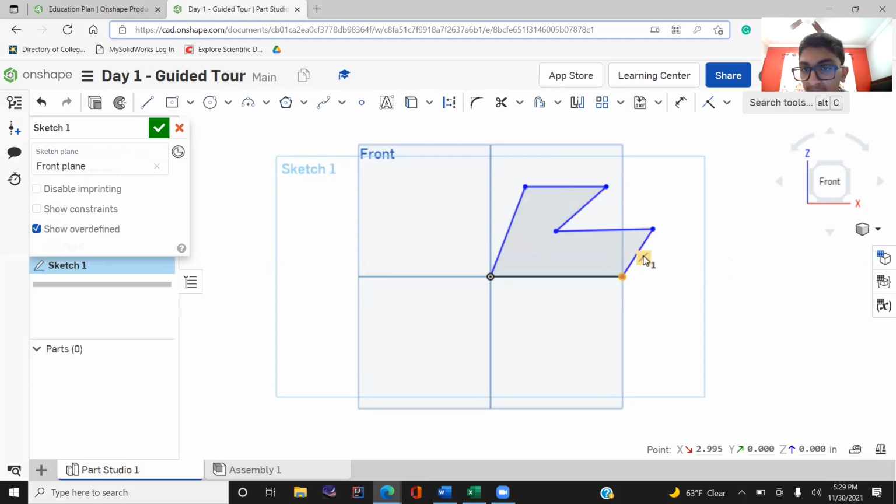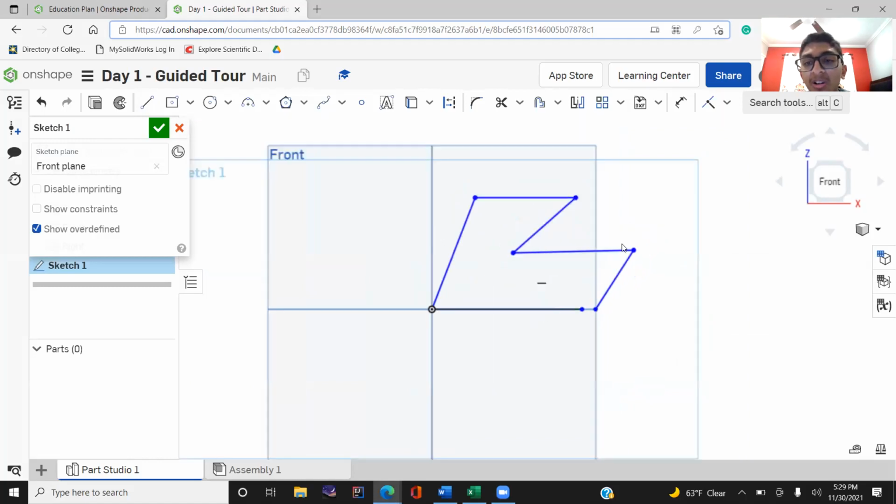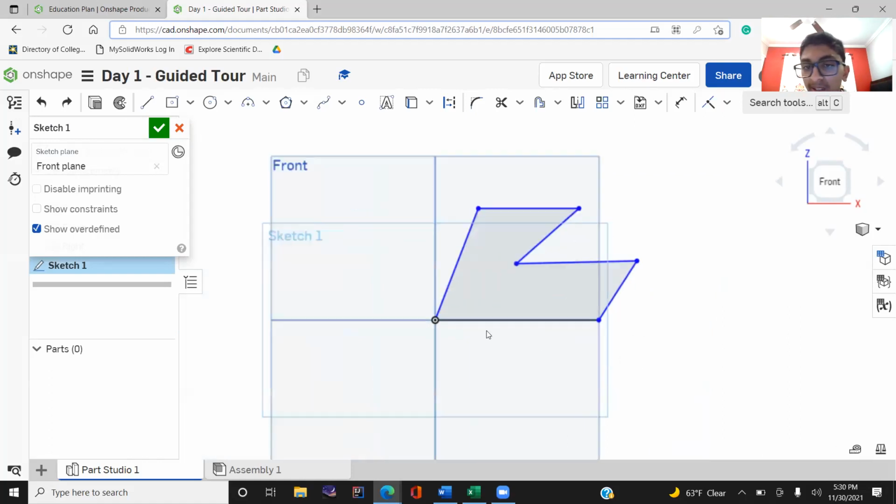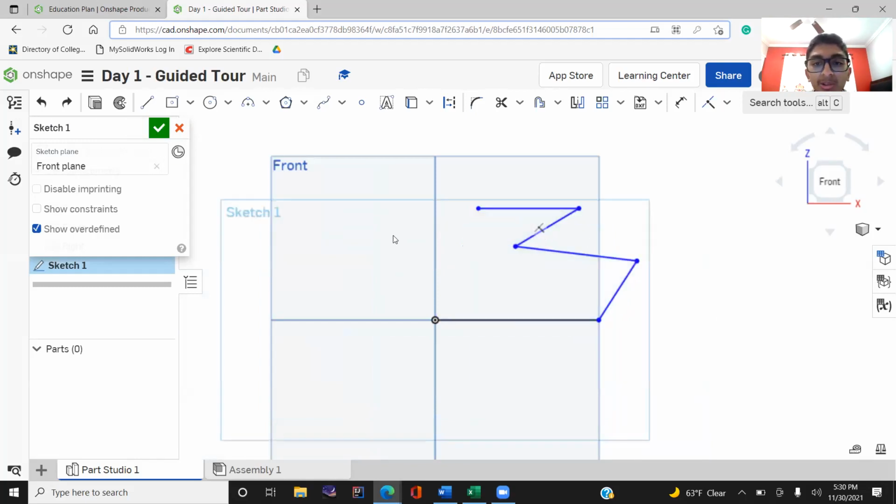For example, we can just delete this constraint here and have these touching each other, not touching. So you'll see here, if you were CADing in a hurry, and you accidentally didn't make these touching or didn't make these coincident, that's the technical word for it, then you might wonder, why is this not a closed shape? Why can I not extrude this and give it a third dimension? The reason is this is not constrained. So if we undo what I just did and make this a closed shape, this is good. So that's the line tool.